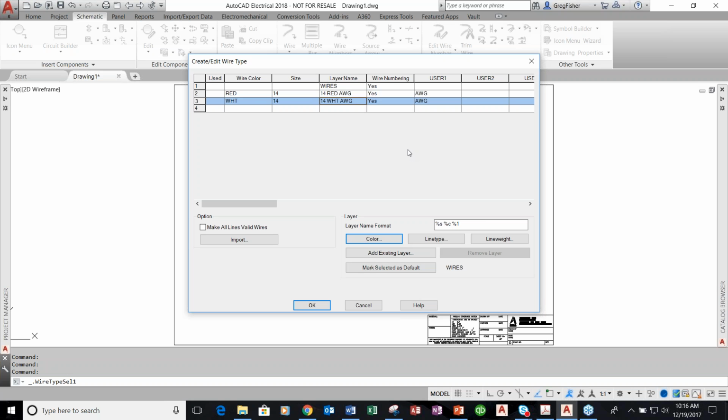And we usually recommend for your drawing templates loading this up to the hilt as far as how many combinations of sizes and colors of wires that you use. You can also put your most popular ones in the template, then maybe add one here or there as you need it. But you should never have a drawing template where you have one wire layer. You're wasting your time. So let's say I would continue on and fill out 50 of these. I'll pick OK.